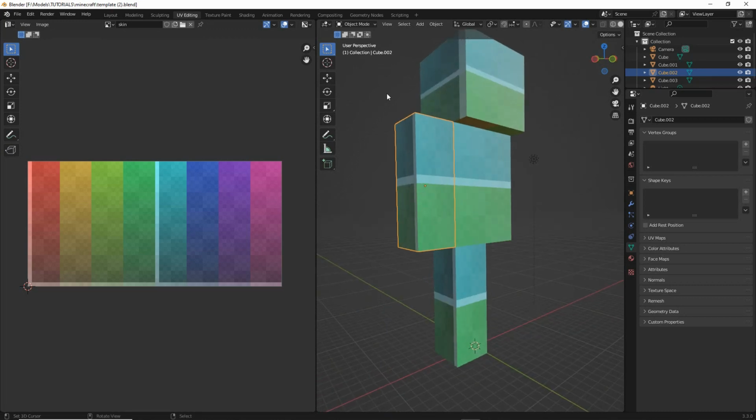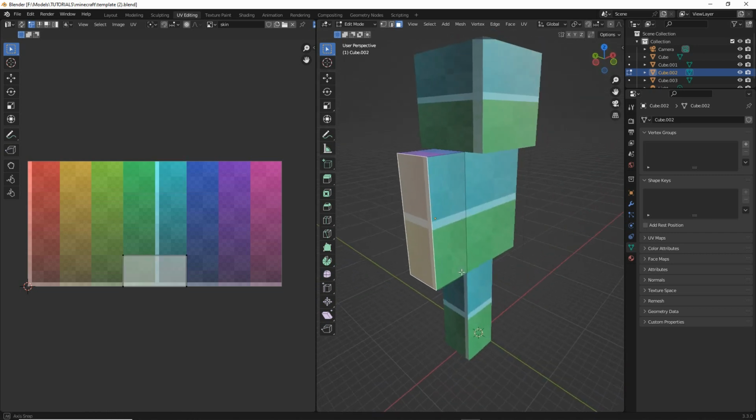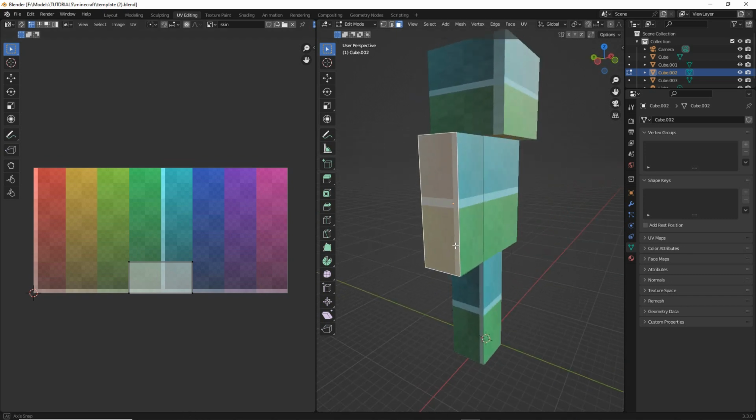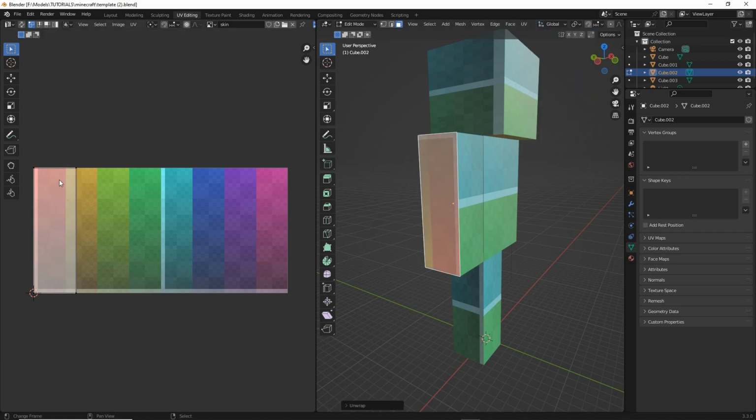And the easiest way to do this is to select our object. So edit mode, we want to switch to face select. And then we're going to select individual faces. So select, and then from the UV menu, so either in the 3D view or the UV editor, UV unwrap, and that'll just remap that UV to the shape that we need.